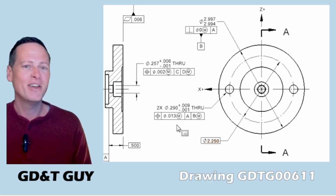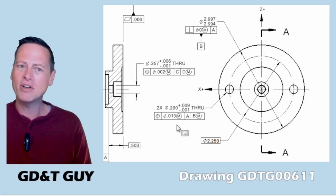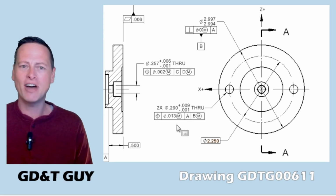Far from it. And it isn't just me. A lot of these ideas are things that I have learned from the people who I have worked with and considered the great GD&T minds. Unfortunately, I think the standard has a little bit of a blind spot when it comes to this. Most of the figures, the illustrations, show parts that are constrained in 6 degrees of freedom by datum features. Most of the figures, okay? But not all. There is one carve-out that we're going to talk about in this very video, where the standard specifically allows only 5 DOF constraint.